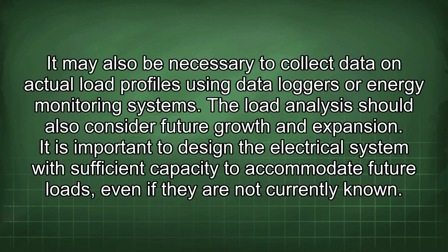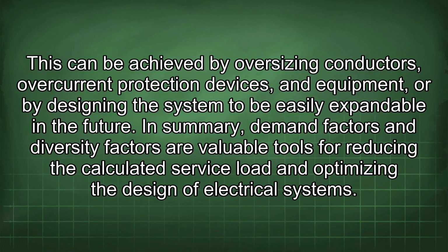The load analysis should also consider future growth and expansion. It is important to design the electrical system with sufficient capacity to accommodate future loads, even if they are not currently known. This can be achieved by oversizing conductors, overcurrent protection devices, and equipment, or by designing the system to be easily expandable in the future.